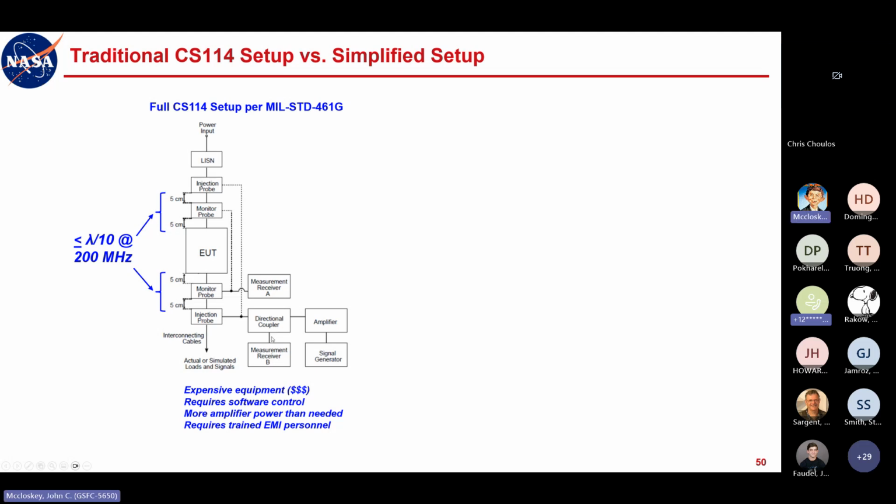Now, when I took a full day, multiple day course on mil standard 461 testing a number of years ago, one of the things that was pointed out, and this is a more complicated setup, is that if you ever encounter this, if your signal generator or even your amplifier craps out after you've done your pre-calibration, and you have to replace either one of them when you're injecting into your cable under test, strictly speaking, you don't have to do the calibration again if what you calibrated against was a power reading out of your directional coupler.